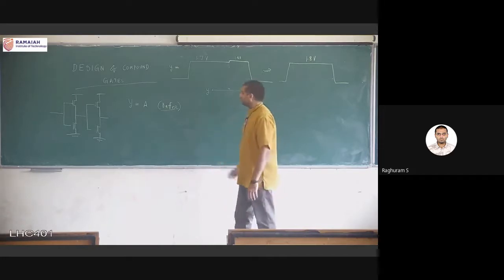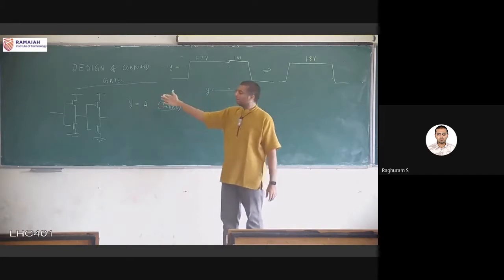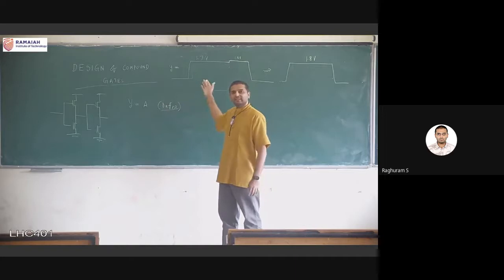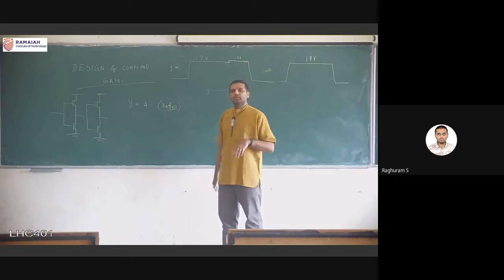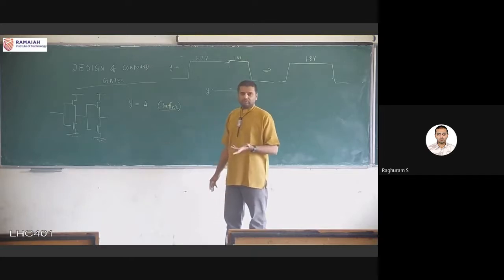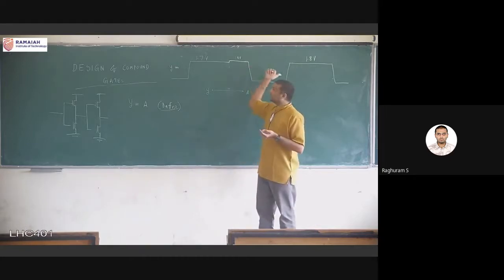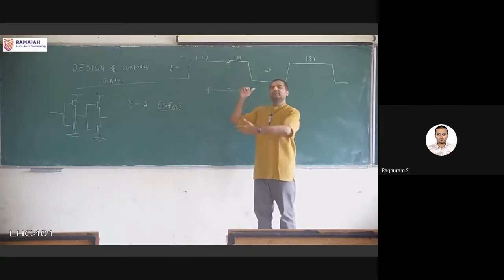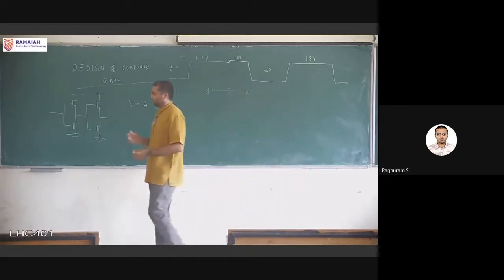So this is the very simple circuit. You can have multiple ones also. There is no reason why I didn't put 4. I can put 2, I can put 4, I can put 6, any amount, to design what is called a non-inverting buffer. If you put an odd number of inverters, you will get an inverting buffer. But in both cases, 2 things will happen. One is the signal will become the perfect value. Another thing that we will see later on is it will improve the timing. So this is one example.